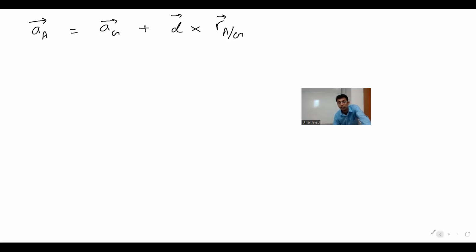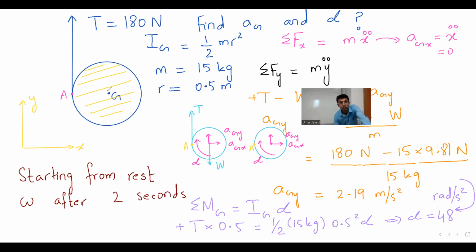Look, everyone, you found the acceleration of point G. You found the alpha. I want you to give me the acceleration of this point. The acceleration of that point A is the same acceleration, because if someone is pulling it from here, then right at that point of contact, whatever A is, that is the same A with which someone is pulling that thread all along, right?